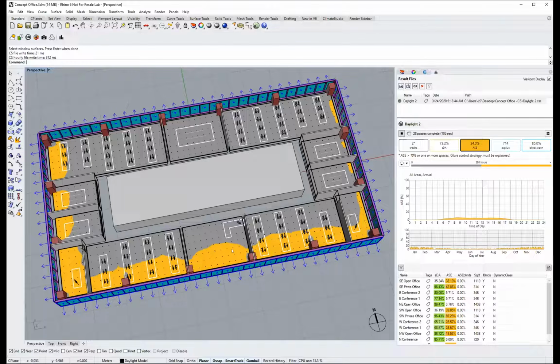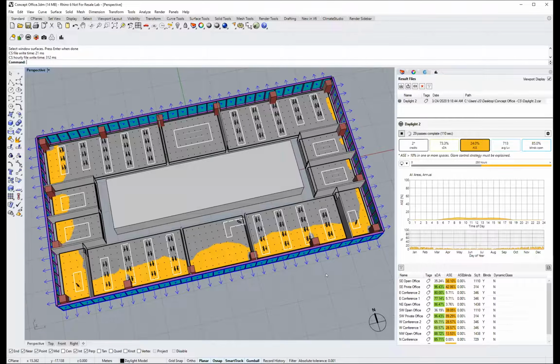And that's quantified as areas that receive 1,000 lux direct for more than 250 hours in the year. At this point, we really have 2 options for LEED accreditation. So one is we can argue that the places where we have too much direct sunlight don't affect work tasks. So, we could design an interior layout such that these areas don't fall on work surfaces. That's going to be pretty hard.